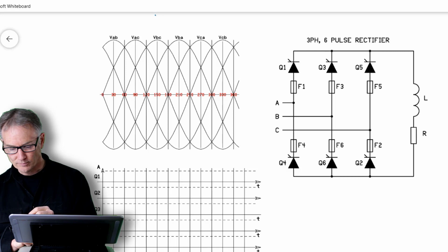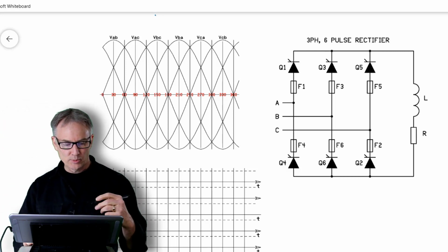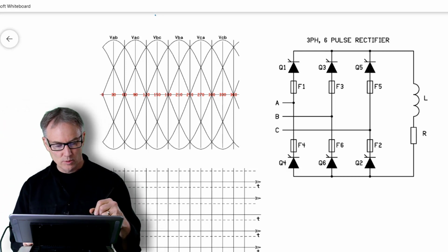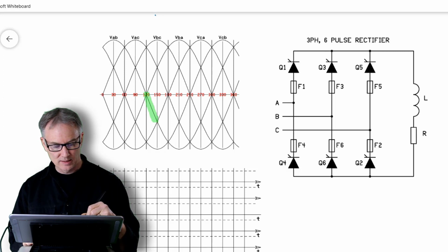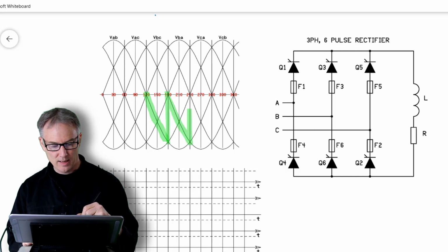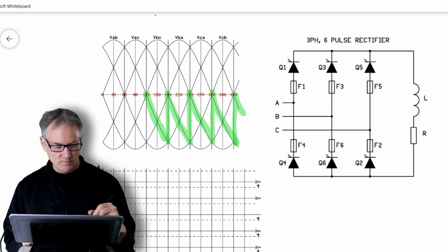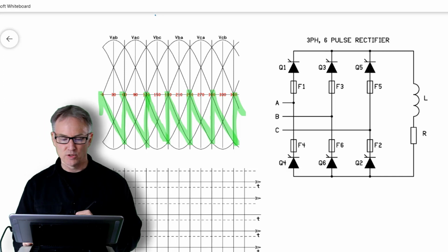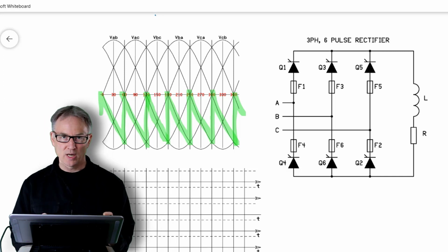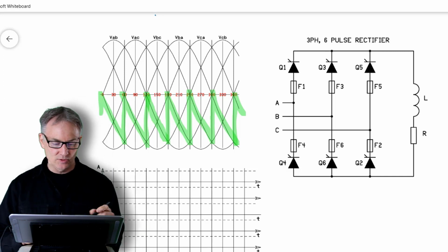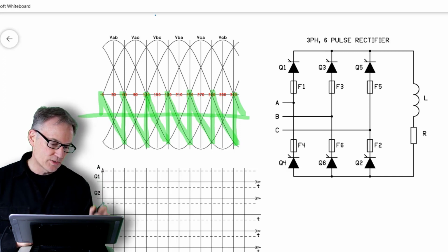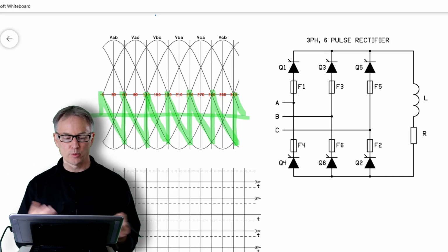So now let's pick off 120. So follow my VAB all the way down to 120 and then continue on that line-to-line voltage and just keep painting that off like that. You can backtrack that and that's your waveform. So the entire time you're firing at 120 degrees, your average voltage is now less than 0. In other words, it's negative.